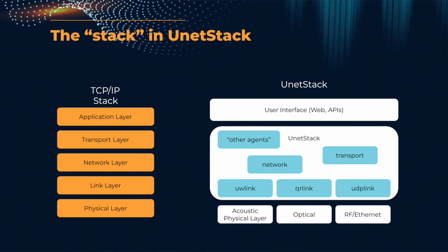But if I have a third guy in the picture, just like all of us are here, I am talking, all of you are listening, that's great. But what happens if all of us start talking? None of us can make sense of anything. So we need to come up with some schemes for when each of the guys goes. Either one person talks one time, and the second person talks next time. So it's a round robin thing. I'm just dividing the time for different people to talk. That's called TDMA. Or I can use different frequencies to talk, or different languages so that not everyone understands.